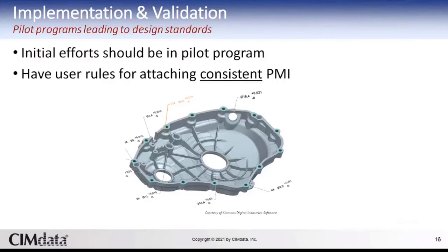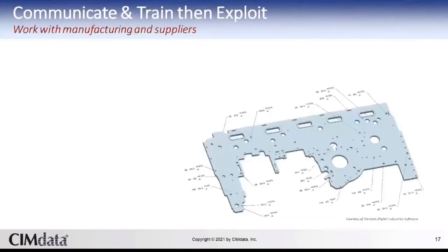It needs to be in a stable form and content to be consumed by those apps. Simply telling your designers to create PMI this way does not guarantee consistency. We recommend you use whatever tools are provided in your CAD solution to assist. And if you have the capability to do a software-driven check, do so, since it's the validation process that will help you catch errors.